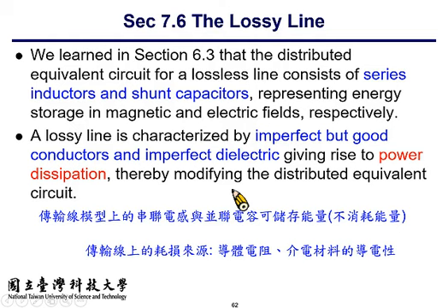So then why can't we draw the equivalent circuit? Why should we adopt the so-called distributed circuit? Because the size, the length, the dimension of the transmission line circuit is comparable to the wavelength of your frequency of interest. Because their sizes are comparable, the wave or the signal that goes in the transmission line only observes the circuit geometry in front of it.